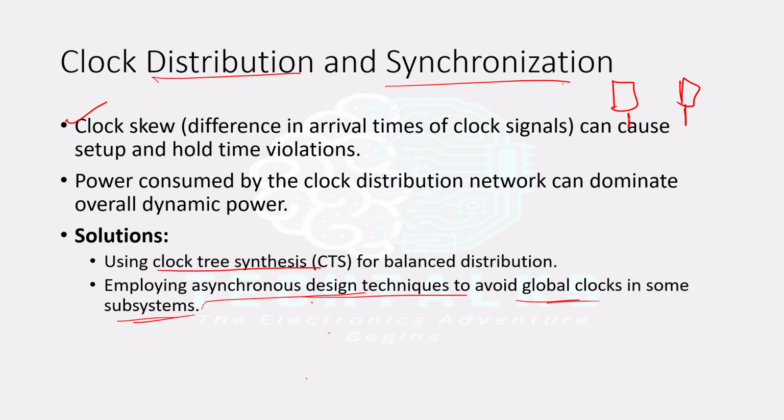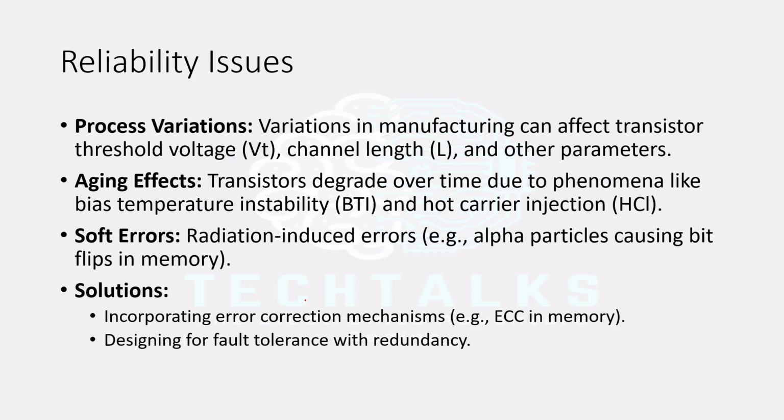For example, you need to interchange data between two modules, and you have the freedom of choosing a communication interface. It is better to go for UART, because as it is asynchronous, you need not sync the clocks, and skewless clocks are not required.